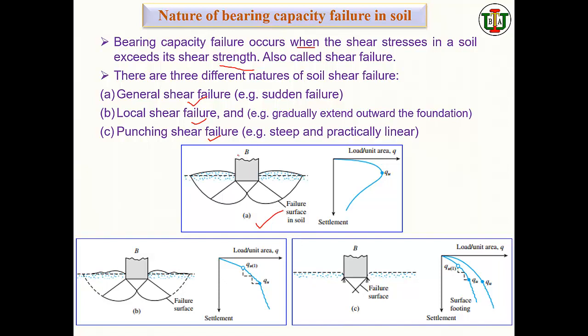This is the width B of this foundation, and the load is coming right onto the foundation. So this foundation will show this kind of behavior after general failure. We can see the failure surface will be developed like this. The shear failure surface of this foundation will be like this, right? Similarly, this one also. And you will find some heaping here, a regular heaping here, while it settles, while it goes down.